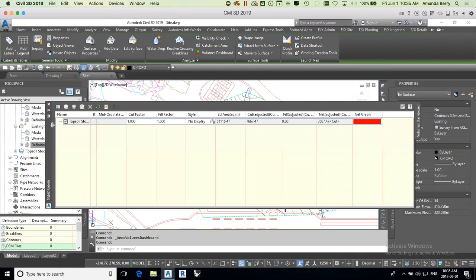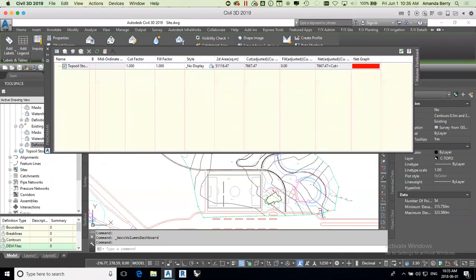And I mean, you could really do that with just a simple hatch or a land effects volume, but by setting it up this way, you are allowing yourself to then also set subgrades of your proposed surfaces as well in the exact same way. And you can start doing volume calculations between the two subgrades to get your total cut fill. And I use this a lot to eventually reduce my cut fill costs and ideally grade my site so that I can have as close to a net zero cut fill as possible. And it really saves the client a lot of money that way.